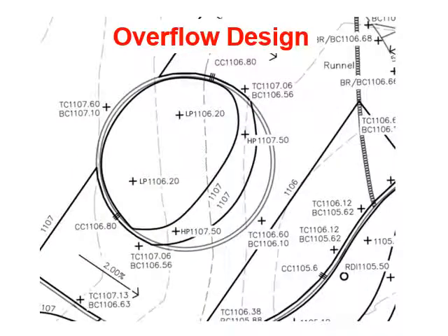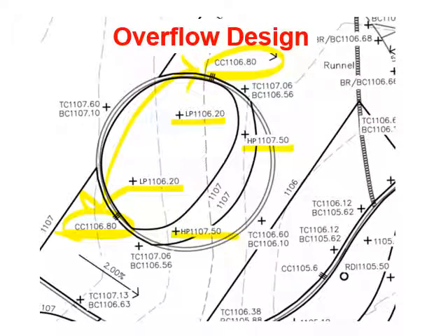So in terms of the details for the elevation, let's make sure we understand. Again, these curb cuts must be at the exact same elevation. And the reason is, if they're not at the same elevation, water will simply flow out of one of the curb cuts. You have to designate the low points within the system. You have to designate the high points that make up the berm. Again, you'd like those to be at least a half a foot above the curb cuts.